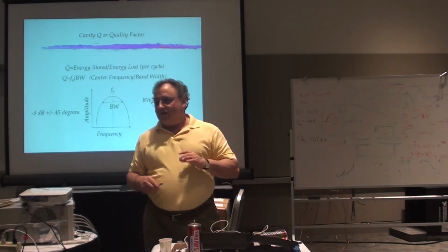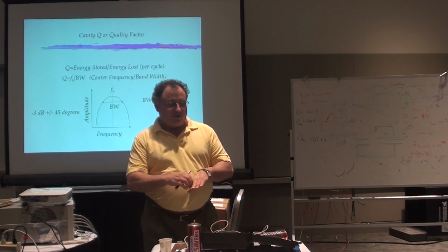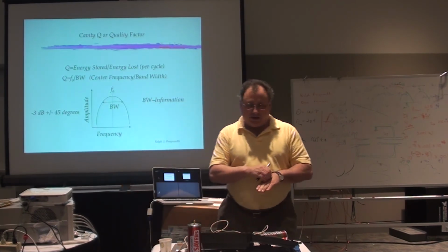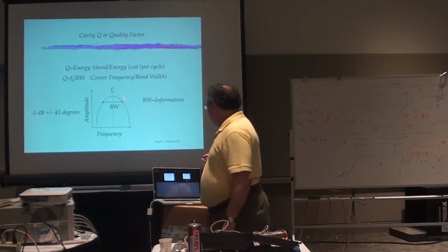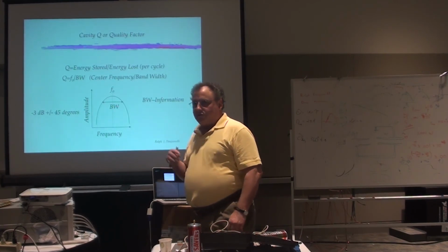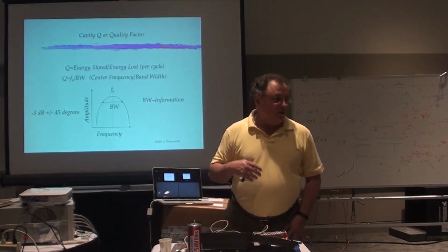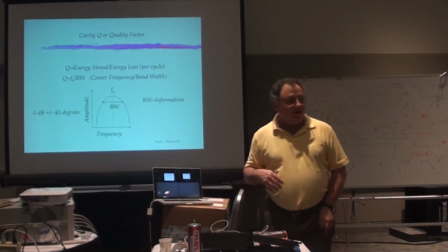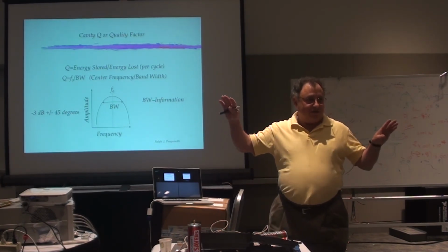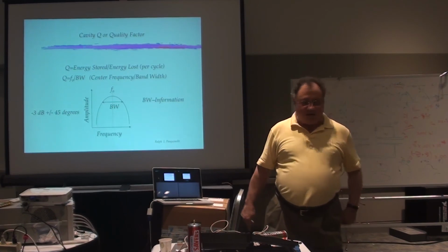Well, that is very tedious. You may even read that in the Adams book, for instance, that talks about doing that. But generically now, I think if you have a simple cavity without ripples and everything else, the 3 dB bandwidth can be considered the noise bandwidth as well. But the real bandwidth of a system is the integral of its entire bandwidth for, say, the gain that's above 0 dB.